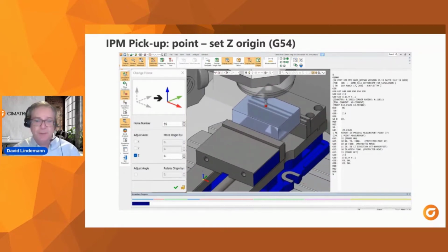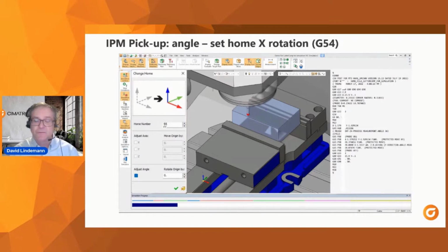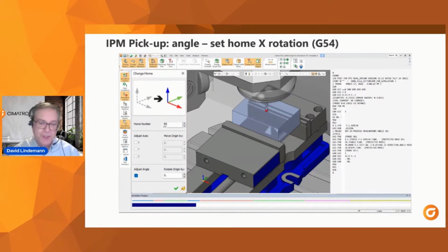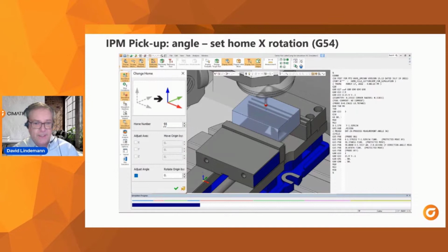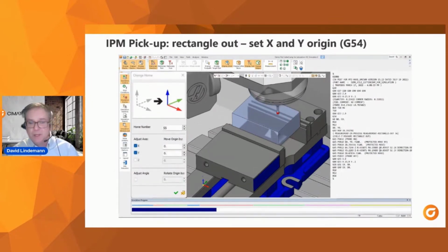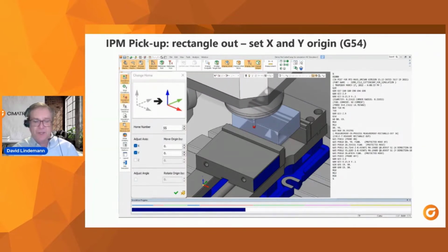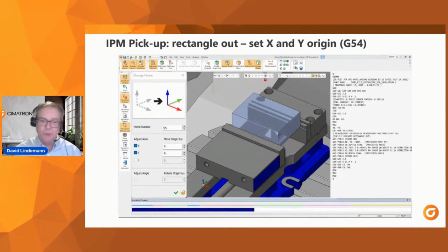And simply here, I'm just going to touch a point for the Z, and we're going to program that for G55. And now we'll come along the front. 2 probe touches here to see if there's any angle in our setup. And then we'll come along both sides and then go front to back. I picked G55 as my work offset, could be whatever you prefer to work with.